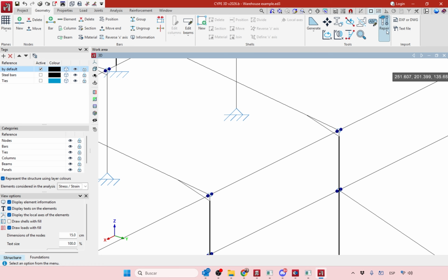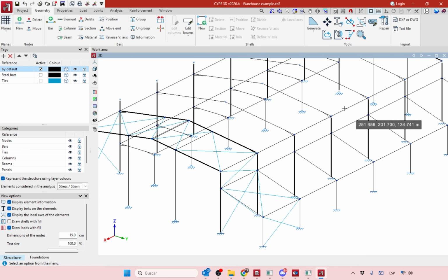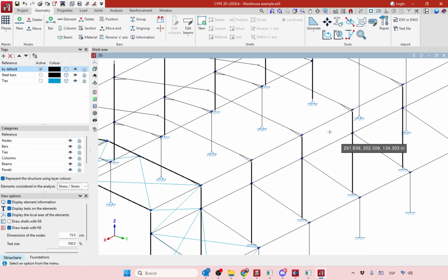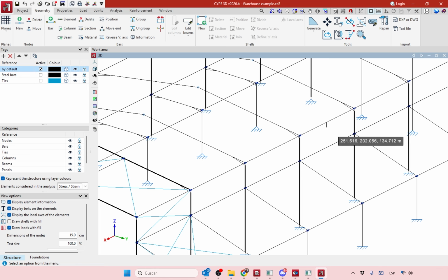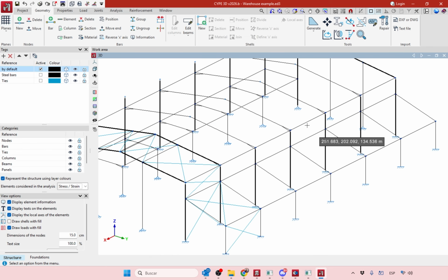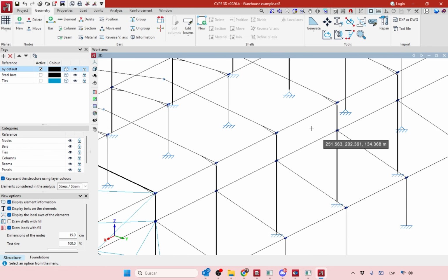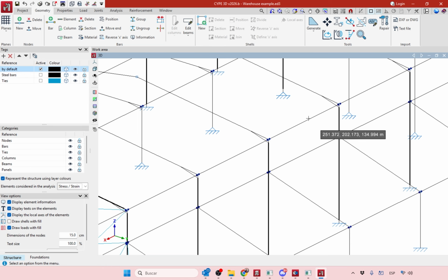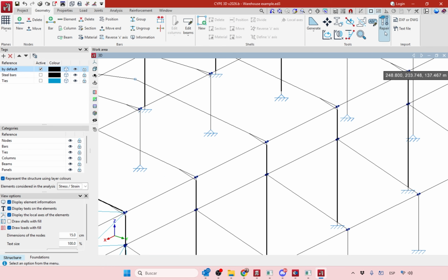Okay, so this button is here. If you see any information on your screen telling that there are two nodes with a distance less than 1 millimeter, probably it's an error, because for a structure of this size, it's too difficult to have nodes with that distance. So you can use this option to repair. Okay, beside that, we have this button that is also new, assign reference.